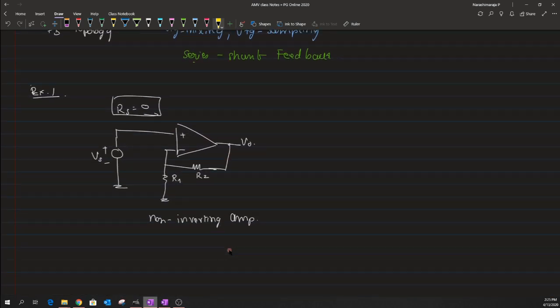Now let us see whether we can identify that component. In this case, this triangle, the op amp that I have here, represents my open loop amplifier, or the basic amplifier. The input of that is supposed to be Vi. Now we know that this Vs is supposed to be a summation of Vi plus some feedback potential in order to create the series shunt feedback network.